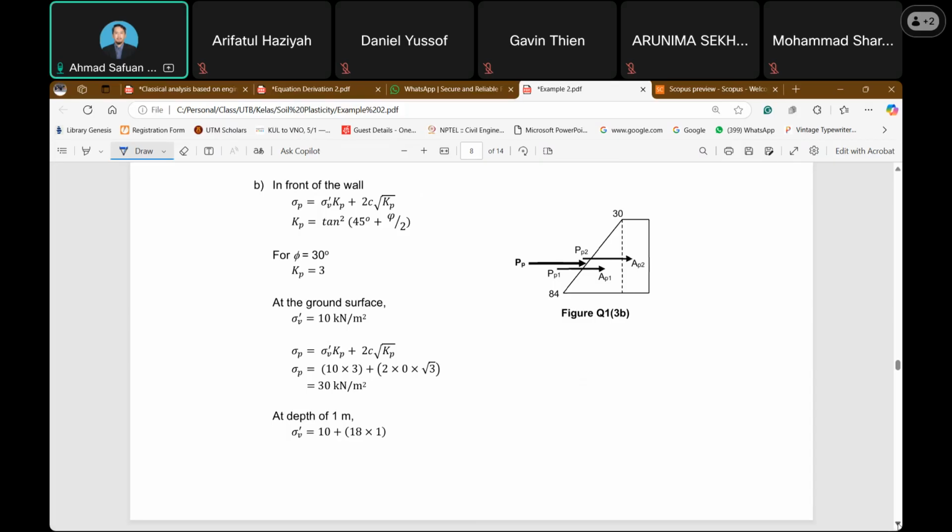So the last one, the line of action, is the total moment of area figure 13B about the base of the wall divided by the area. So from there, Y average, we obtain 0.42 above the base of the wall.